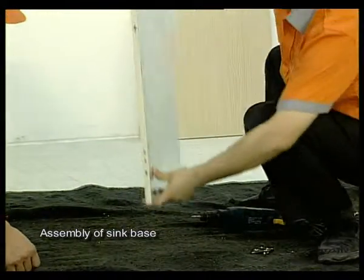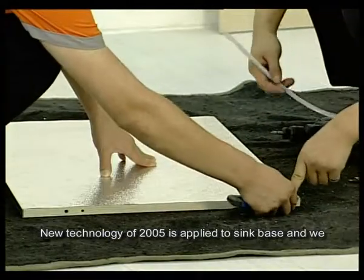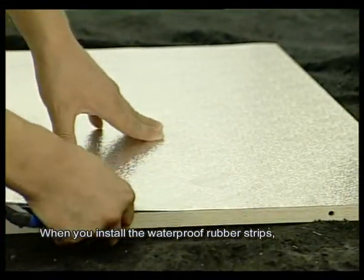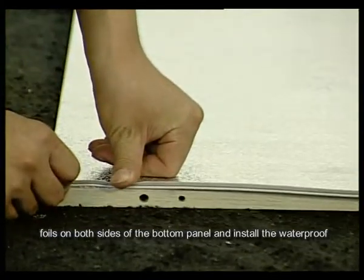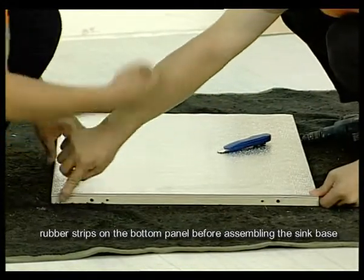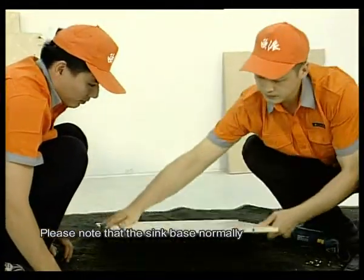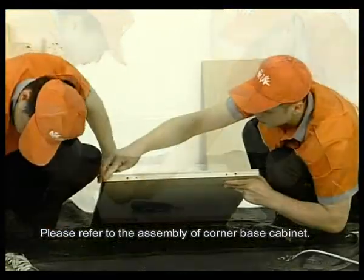Assembly of sink base. New technology of 2005 is applied to sink base and will incorporate waterproof rubber strips on the bottom panel. When we install the waterproof rubber strips, use a knife blade to slightly push up the aluminum foils on both sides of the bottom panel and install the waterproof rubber strips on the bottom panel before assembling the sink base. Please note that the sink base normally does not have a back panel. Please refer to the assembly of corner base cabinet.